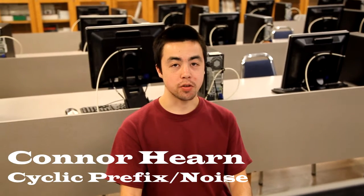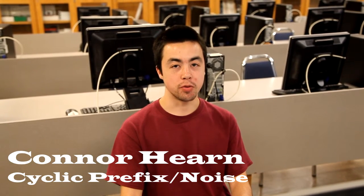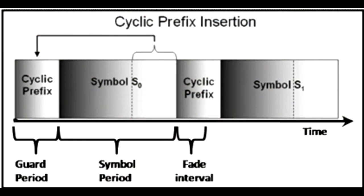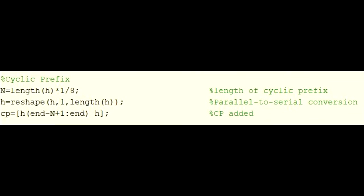The purpose of the cyclic prefix is to eliminate inter symbol and inter carrier interference by copying the end of a symbol and pasting it to the front. Carriers can be delayed, causing the system to lose orthogonality, but it is restored by converting the linear convolution of this channel to circular convolution. For the cyclic prefix to function correctly, the length of the cyclic prefix should be longer than the channel impulse